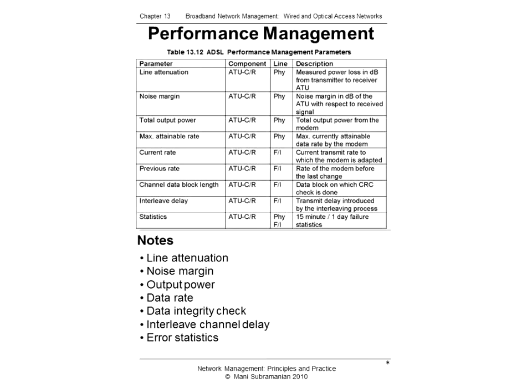This table shows the performance management. Here each ATU performance is measured in terms of line attenuation, noise margin, total output power, current and previous data rate, along with maximum attainable rate. Channel data, block length, and interleave delay can also be monitored.